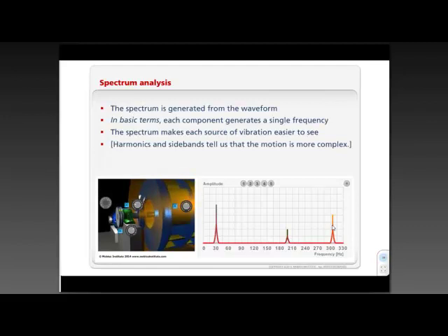This will be 14 times, well, in fact, I can look at the scale and I can even work that out for myself. That should be sitting right at 10 times the speed. So we've got 10 blades, 10 times the running speed is 300. I haven't got it quite lined up perfectly, but because I can alter the frequency just a little bit. There you go, that looks better. And so at 10x, 10 times running speed, we've got this peak that's due to the fan.